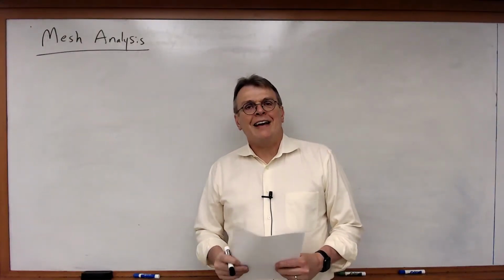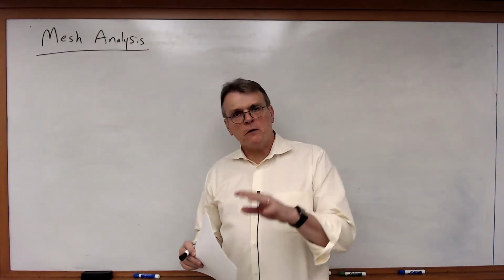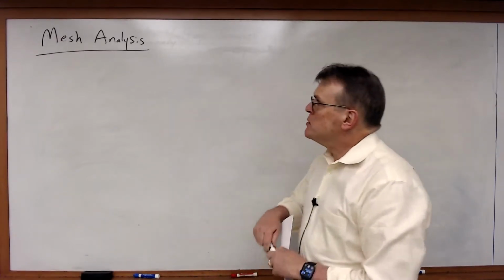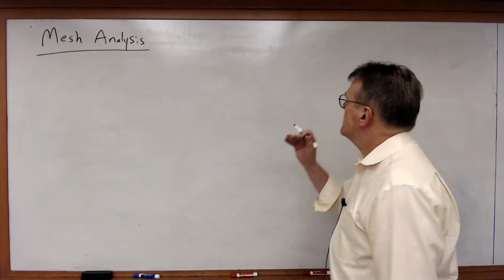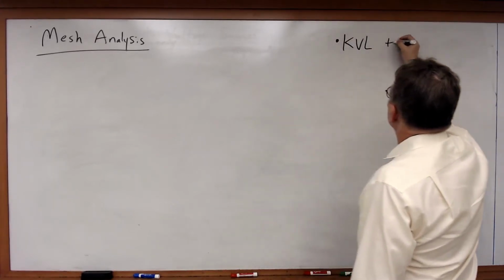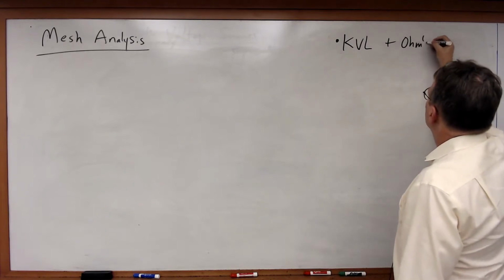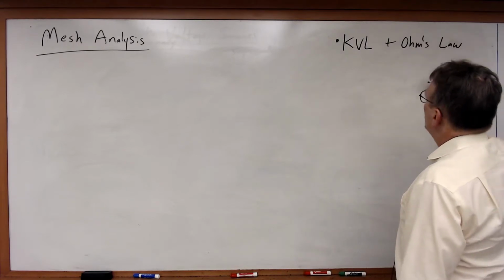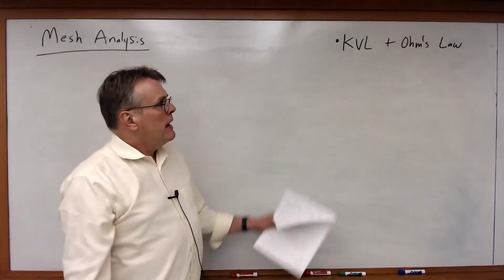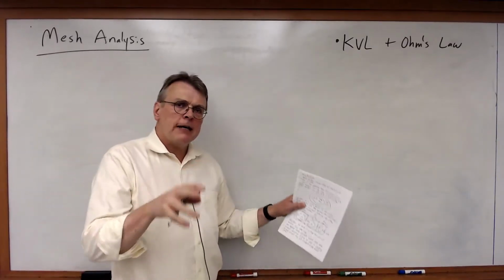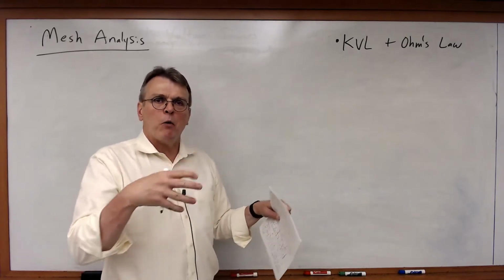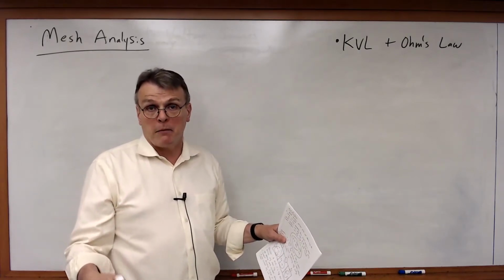Now let's look at mesh analysis, which is the other major analysis technique we're going to learn how to use. Mesh analysis is basically, as we're going to see, KVL plus Ohm's law, as opposed to nodal analysis, which was KCL plus Ohm's law. And as we're going to see, in some ways these techniques are kind of mathematical duals to each other in terms of how we're going to approach the solution to the problem.